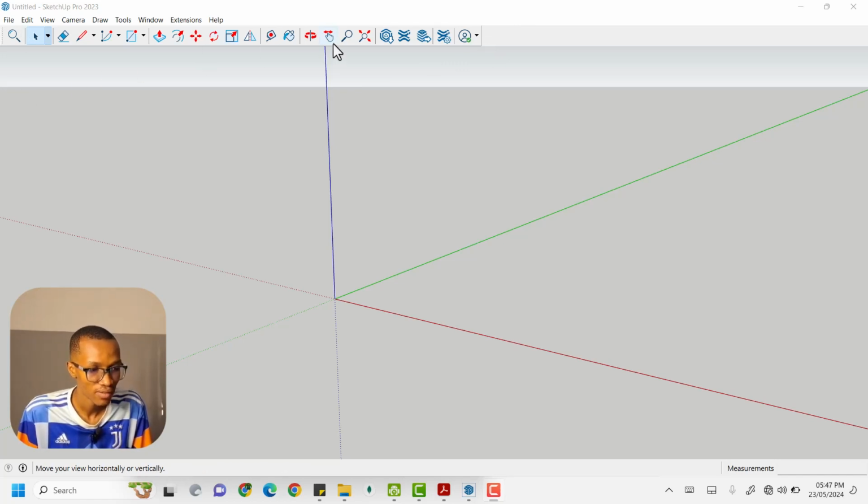So in the last video, we began looking at the 3D and manipulation tools, and we looked at push-pull, which helps us to extrude faces to create 3D forms, offset, which copies edges to create outlines or inset, and our move tool that moves, copies, or distorts selected entities.